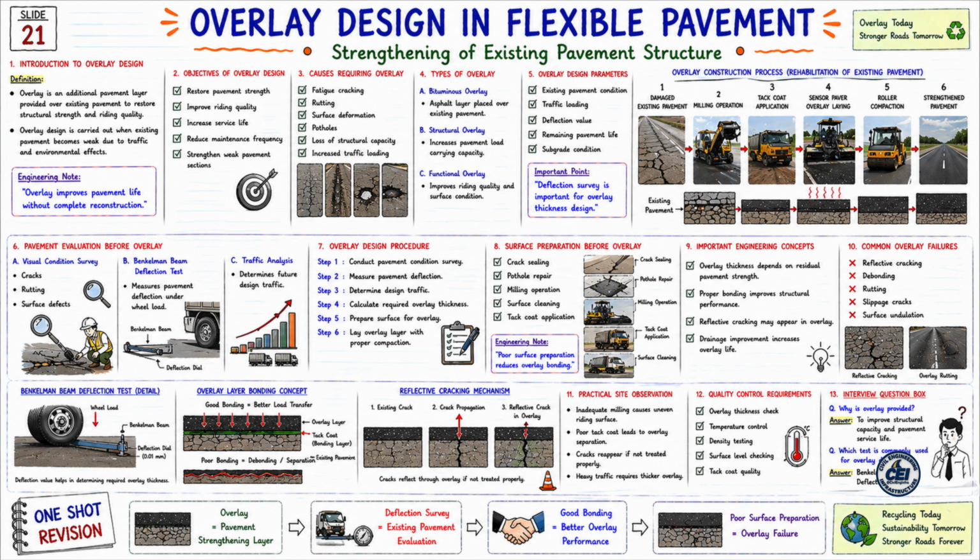Introduction to overlay design. What is overlay? Overlay is an additional pavement layer, which is provided over the existing pavement, so that structural strength and riding quality can be restored. When the existing pavement becomes weak due to traffic loading and environmental effects, then the overlay is provided. See the engineering note below.